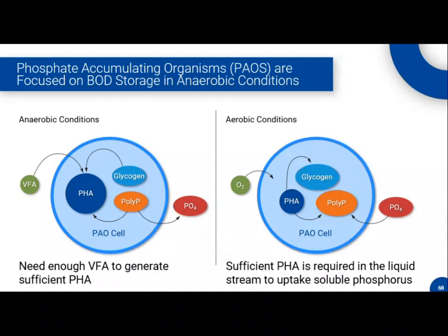It's not that the PAOs die under aerobic conditions. It's just that the heterotrophs outcompete them and grow faster and multiply faster. And so you just wash them out. But when you put that anaerobic condition in, the heterotrophs can't access the VFA. And even though the PAOs get less energy from that VFA, they're the only ones that can access it, right? So we're kind of like coddling them along, right?